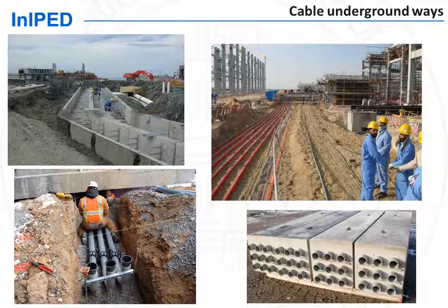Underground cable systems also include duct banks for road crossing, as well as cable sleeves for the cables to go from the concrete cable trench up to the equipment through the paving. As you see, the underground cable systems entail quite a number of elements. In addition, there are different cable systems, including electrical power supply cables, electrical lighting cables, instrumentation and control cables, fire and gas detection cables, as well as telecommunication cables.